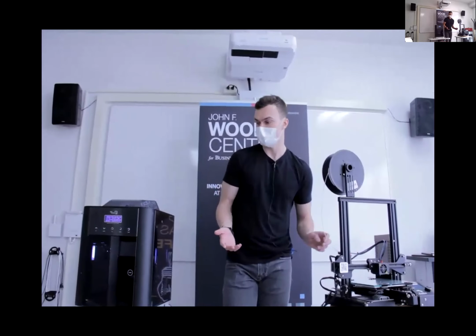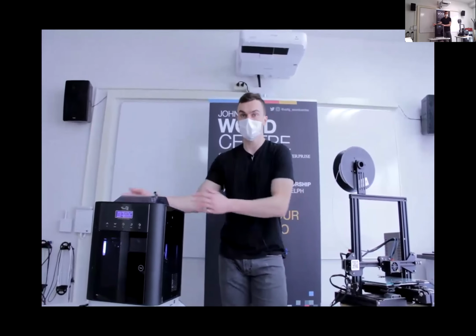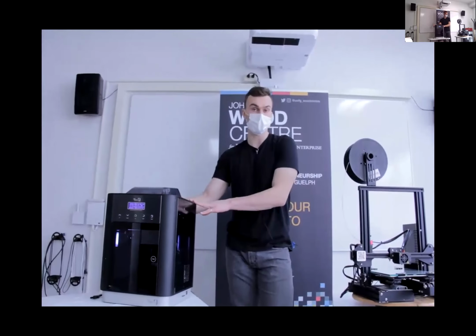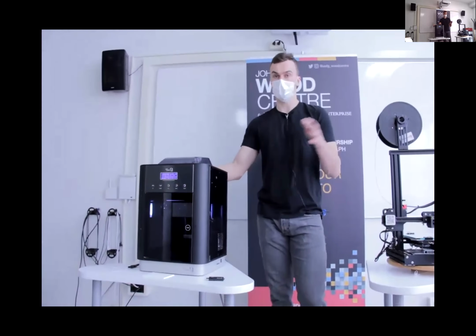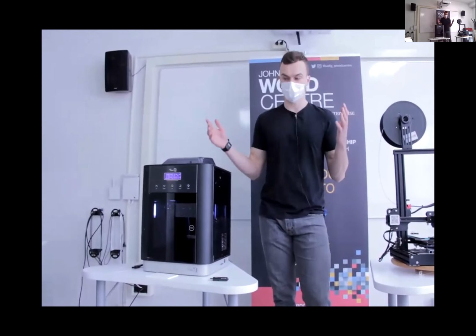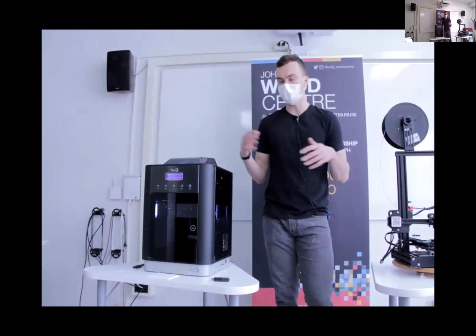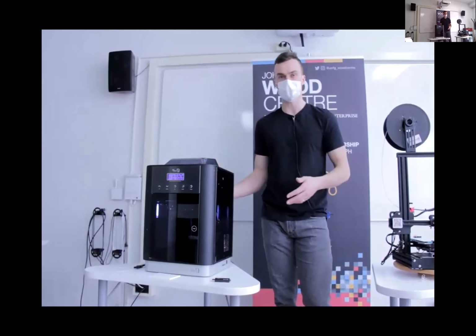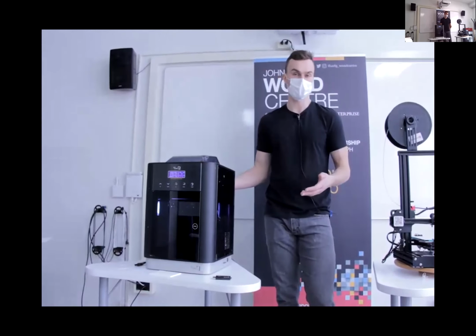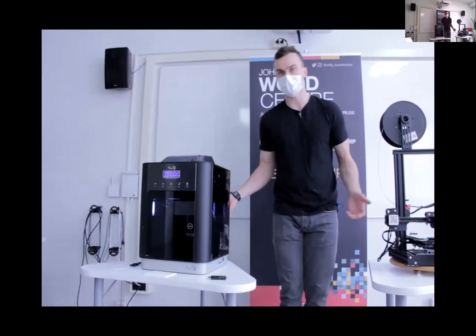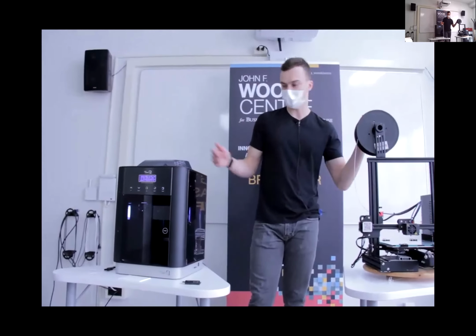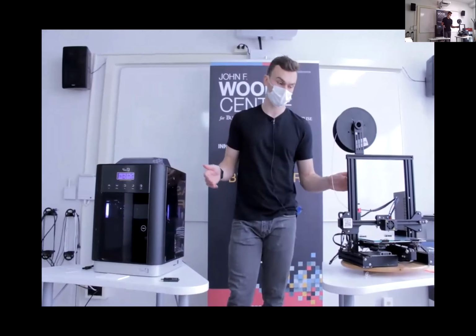Another difference in the two is, like I mentioned earlier, the Cubicon printer is enclosed, so it's more resilient to surrounding air temperature, and it also keeps enclosed any kind of fumes that might be generated by the filament as it's melted. However, PLA is pretty safe, so it's okay to use PLA on open and closed bed printers.